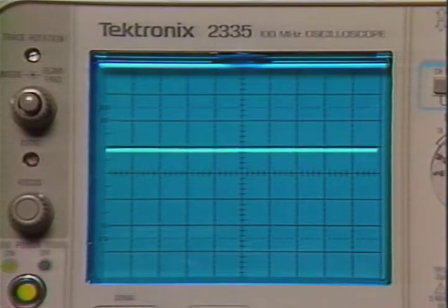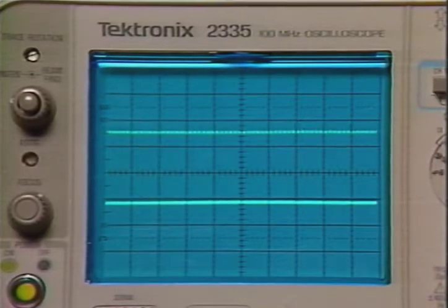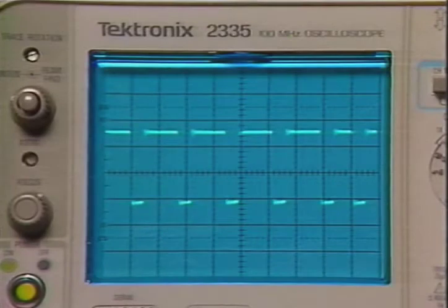For example, on an oscilloscope you can see how much of a signal is DC, how much is AC or changing with time, and the waveform period and frequency. If the signal is digital data, we can measure the pulse width, repetition rate, and in general view the shape of the pulses. Many times it's that shape that's important.